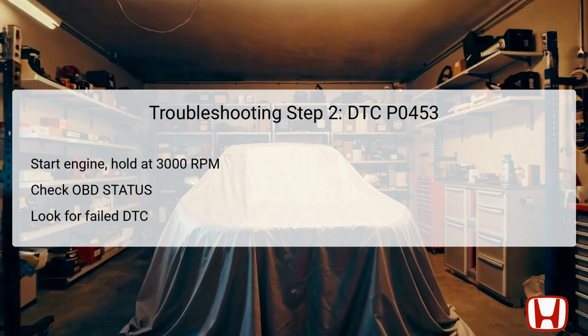In the second troubleshooting step, the engine must be started and maintained at an engine speed of 3,000 RPM while idling without load. This process ensures that the engine is operating at a stable condition, which helps enhance the reliability of the diagnostic results.